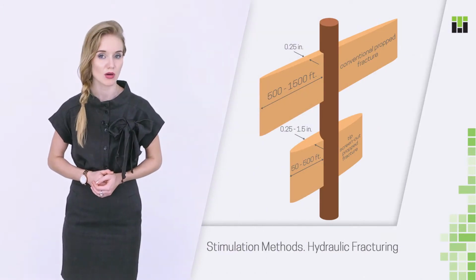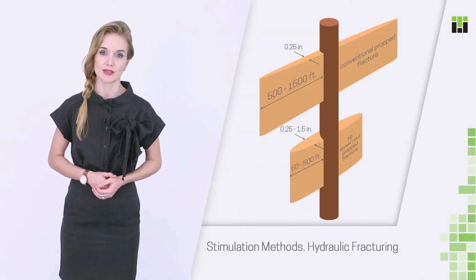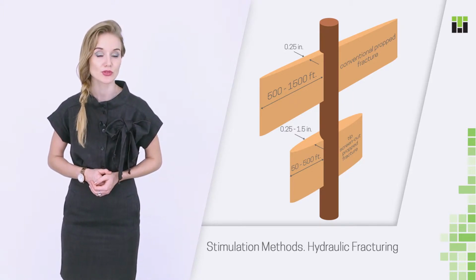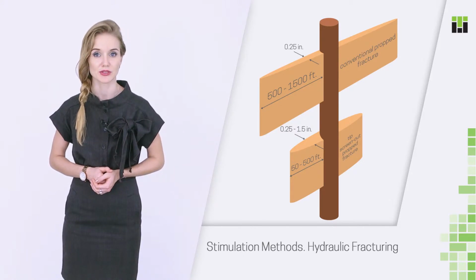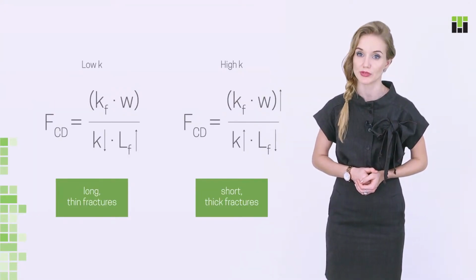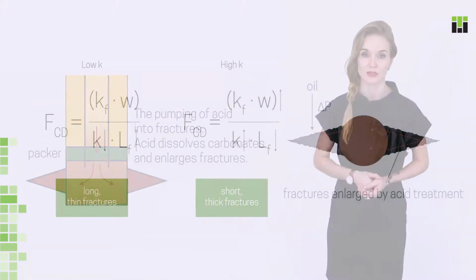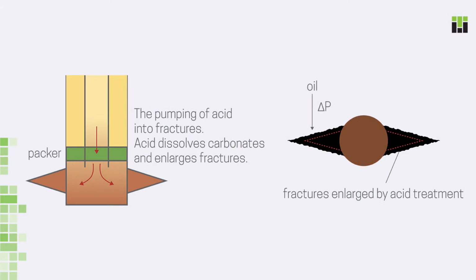Then there is TSO, tip screen out technology. This is a modification of conventional fracturing. Then we create fractures that are extra wide, up to 40 mm. This is commonly done on high productivity wells to decrease flow turbulence and control sand production. And the third one is acid fracturing, when we use acid as a technical fluid. Injection pressure is enough to create fractures, and the acid washes these fractures out, so that even when the pressure is removed, deep, highly conductive channels remain in place.